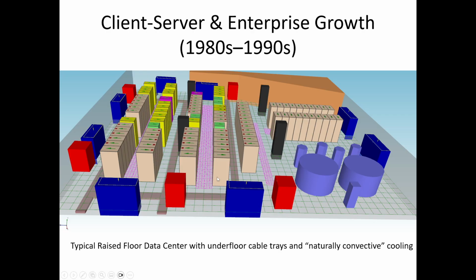Even though these are lined up now, you're seeing the beginning of them being lined up pretty well. The green arrow is the airflow indicator, so front to back. You see the cold aisles here with perforated tiles in the cold aisles, the hot aisles on the other side. So the equipment in this section of the room is lined up fairly well with respect to hot aisle, cold aisle. However, it's not unusual due to evolution to see some not lined up perfectly well. This rack set over here is perpendicular.